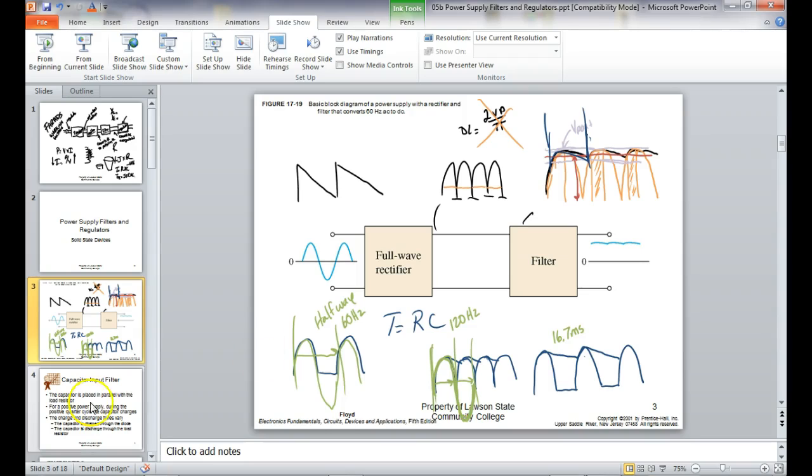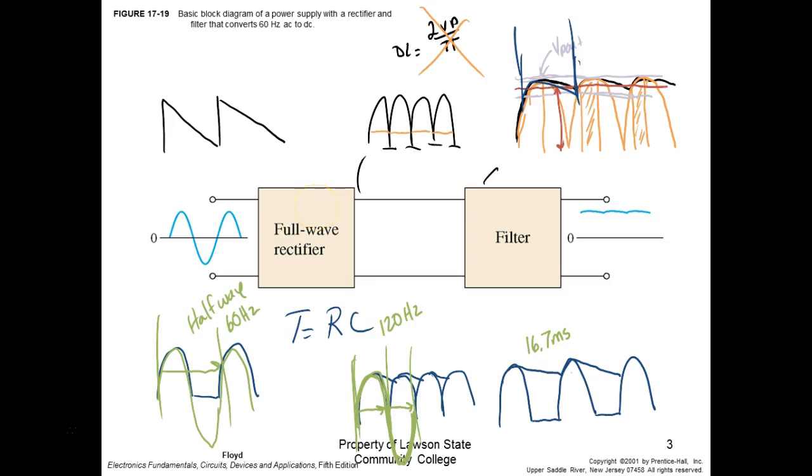Oh, it asked for the pulse frequency out for a full wave rectifier running off 400 cycles. If it's full wave, it'd be 800 cycles, right? If it's half wave, it would be 400. So we don't make y'all do any real calculations. It's just a pretty straightforward question.